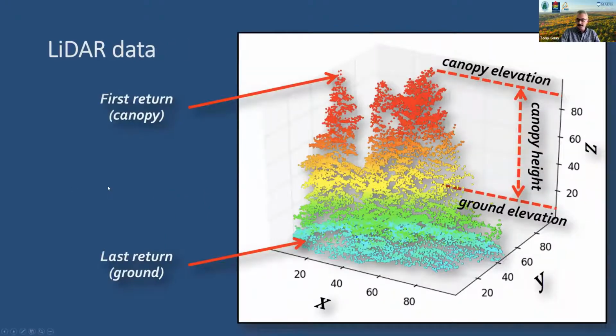All right, so in general, in a LiDAR point cloud, your last return is typically at the ground. Your first return, as I mentioned earlier, is basically the tops of the trees, or whatever that first object is that an incoming LiDAR pulse hits. So it could be the top of a building, could be the top of a vehicle, could be a bird.